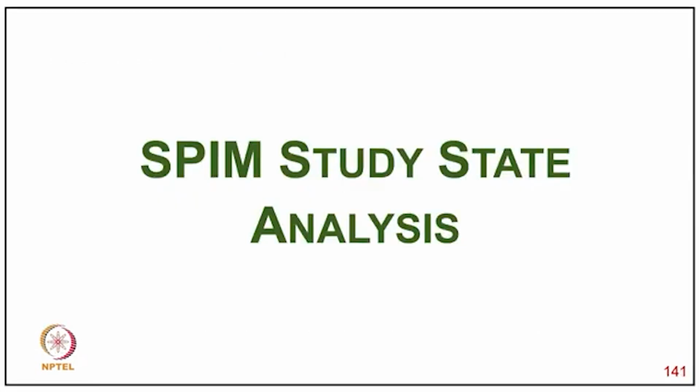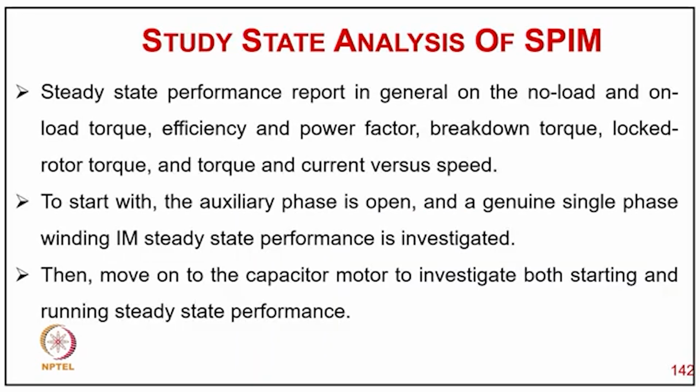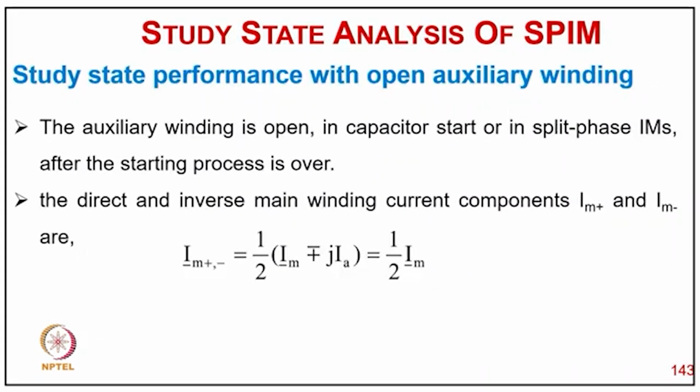Now coming to single phase induction motor steady state analysis. The steady state performance is reported in general on no load and on load, the efficiency and power factor, breakdown, locked rotor and torque and characteristic. To start with, with the auxiliary phase open and a genuine single phase winding induction motor, steady state performance is investigated, then move to the capacitor motor to investigate both the starting and running steady state performance.